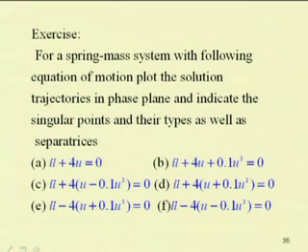Similarly, you can find the trajectory for the case u double dot plus 4 u plus 0.1 u cubed. In this case you can observe the saddle node, separatrix and center. And in this case, u double dot plus 4 u minus 0.1 u cubed. This minus term comes when you have a soft spring. Here also you find the potential well and obtain the response. This is a hard type of spring in which alpha is different, and we have taken a quadratic spring. In the previous case you had a cubic spring; here you have a quadratic spring.